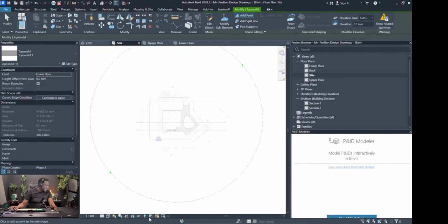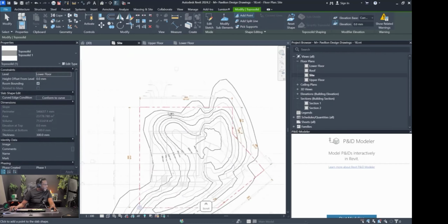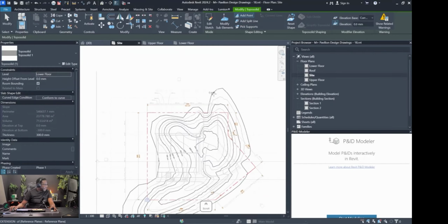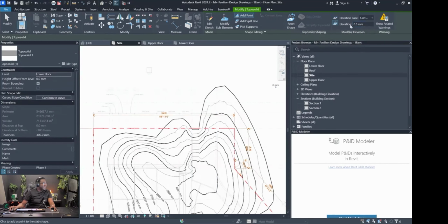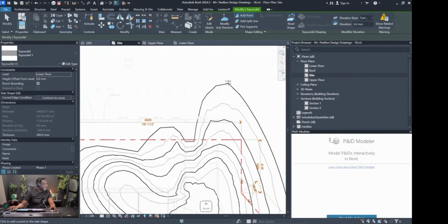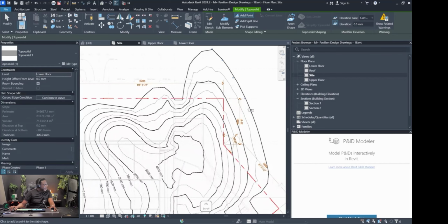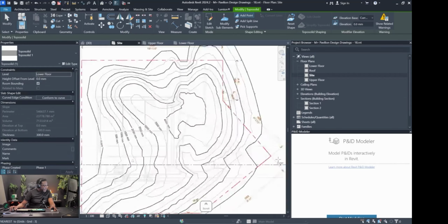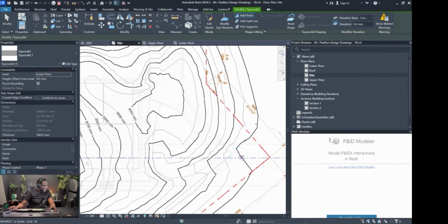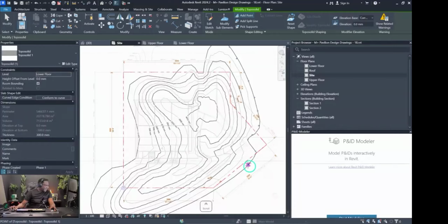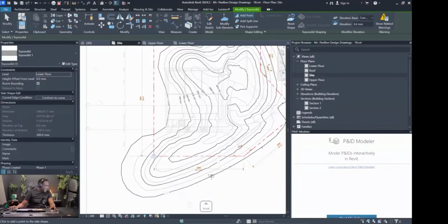So a quick way we can get around this is to just choose wireframe. So now we're seeing just the lines. All right, so at level 0, we're going to add our first point, and I'm just going to start from here. And what I'm doing here, I'm just putting points that are averagely along this line. Now notice that it doesn't have to be exact, but what I'm trying to do is to have them evenly spaced. Like, I'm not trying to put some closer together and some far away. I'm just estimating.